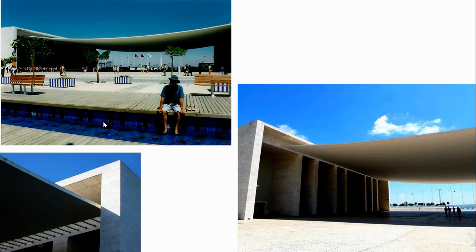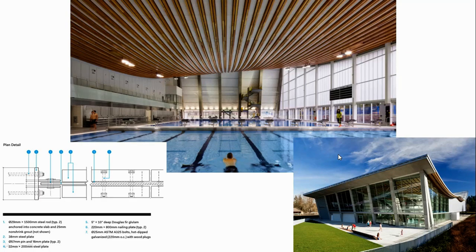It's reinforced concrete. And you can just about see here, quite clearly, the steel reinforcing that is connected back to these big shear walls. So instead of having a mast here and it's tied back, as in some of the buildings we've seen, all that work that's resisting the pull of this canopy is done by this series of shear walls here. They're doing the job of resisting the tensile pull of the structure.